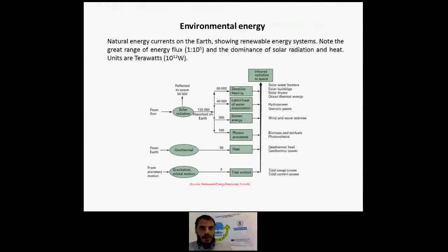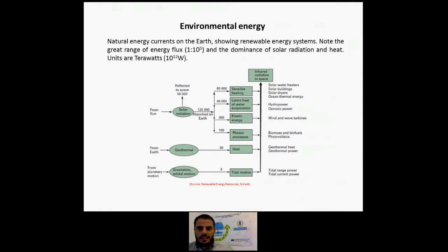In the first instance, the complete energy systems must be analyzed, and supply should not be considered separately from end use. Unfortunately, precise needs for energy are too frequently forgotten, and supplies are not well matched to end use. Energy losses and uneconomic operation therefore frequently result. For instance, if a dominant domestic energy requirement is heat for warmth or hot water, it is irresponsible to generate high quality electricity from a fuel, waste the majority of the energy as thermal emission from the boiler and turbine, distribute the electricity with losses, and then dissipate the delivered electricity as heat, a total loss of about 75%.